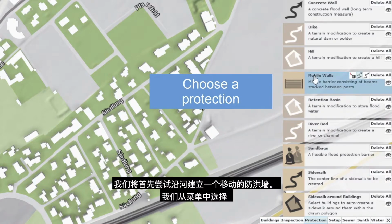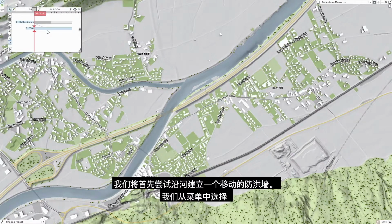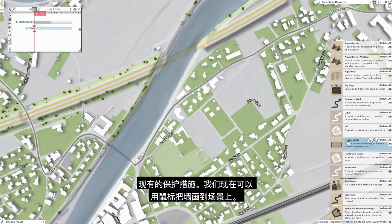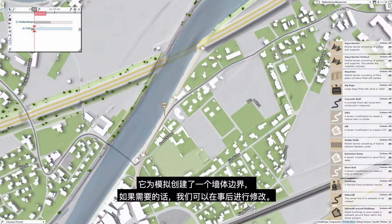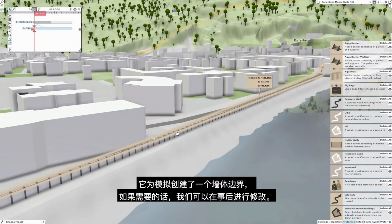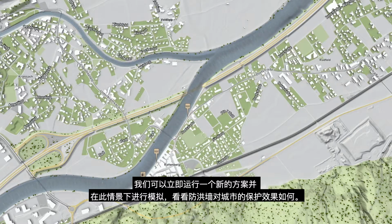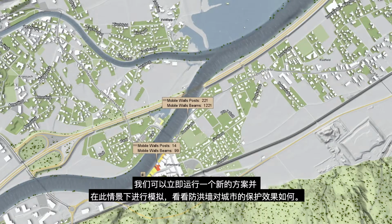We will first try to create a mobile flood wall along the river, which we select from the menu of available protection measures. We can now draw the wall onto the scene with the mouse, which creates a wall boundary for the simulation that we can modify afterwards if needed. We can immediately run a new simulation for this scenario to see how well the flood wall protects the city.